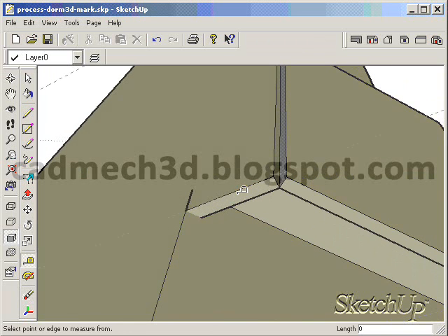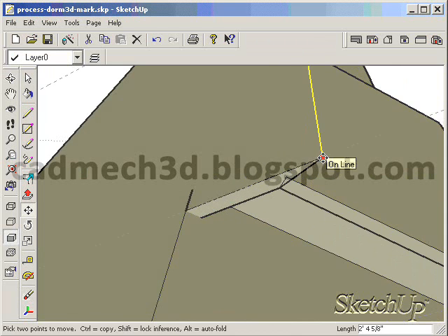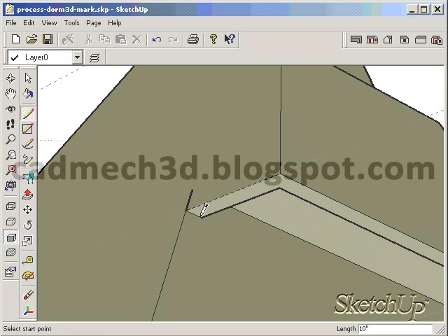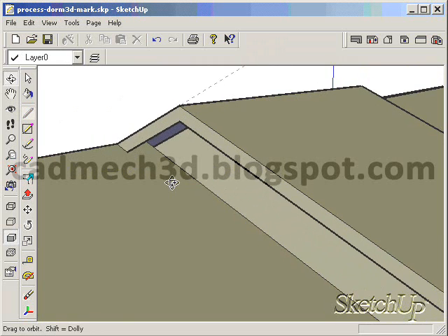Do the same thing here. Select the ridge line, lock the inference direction along the construction line, touch on the plane to align it, grab the other ridge line, move it up to connect, then erase out extraneous lines. Now I can trace out where the edges intersect with the roof planes to stitch together the intersection of the overhang with the lower roof.